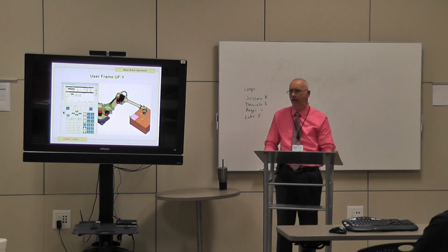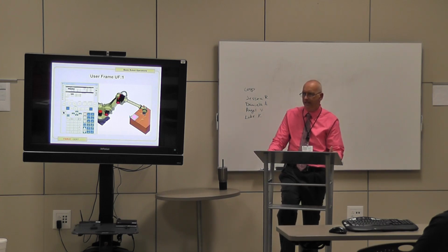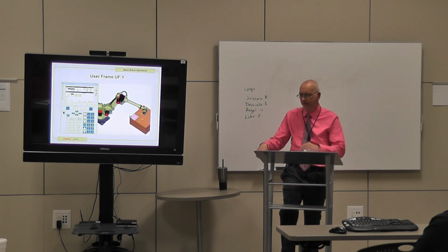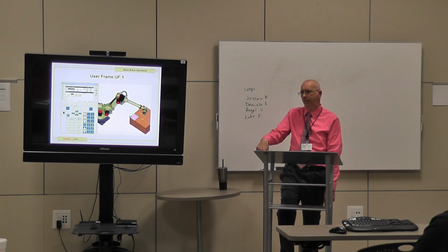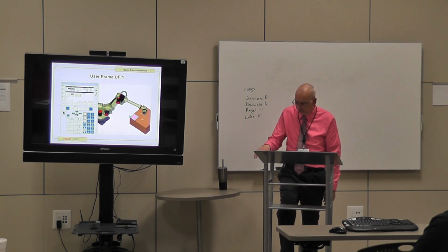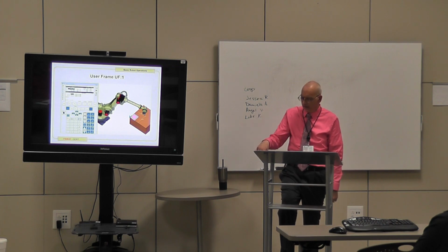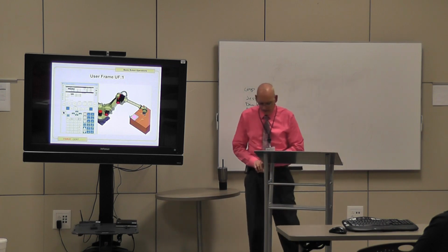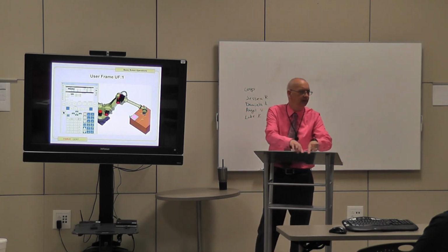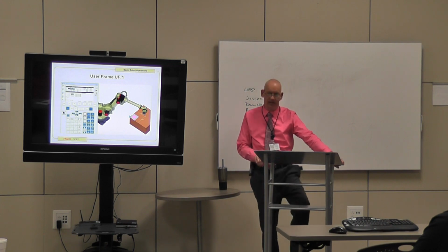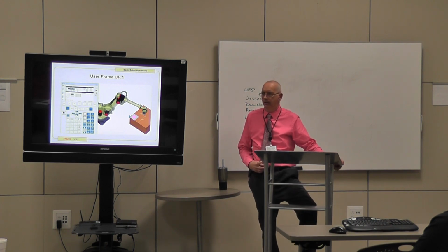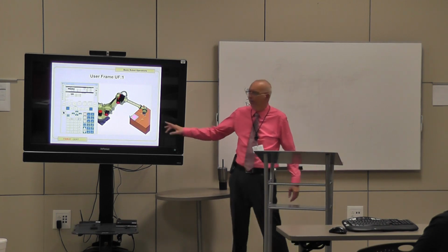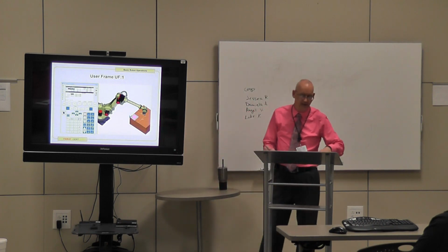Then I would bring my robot and do my method of defining that and making my point of origin, let's say right here, because I don't want to include this. I just want to use the flat part. I make this my point of origin. I have to go out a certain distance this way, okay, mark that, come back to my point of origin, go this way, and that's now defining what my user frame is going to be. Everybody understand how that concept works? Okay? Taking my new point of origin away from the robot and now putting it to the user frame itself.